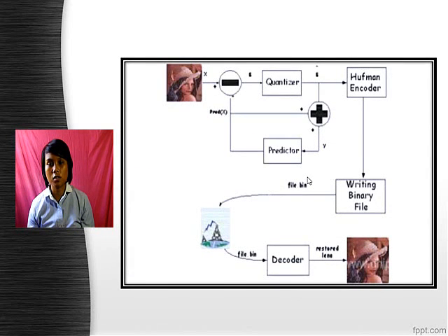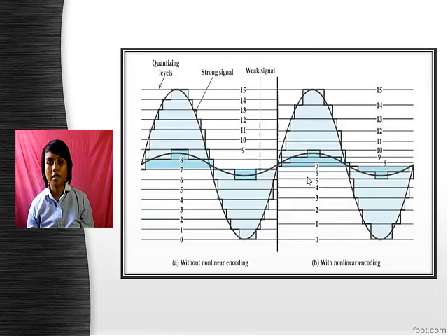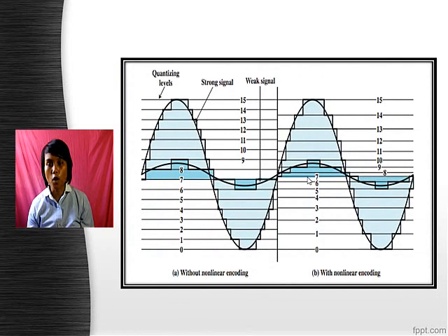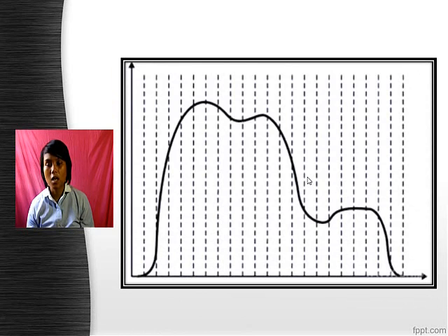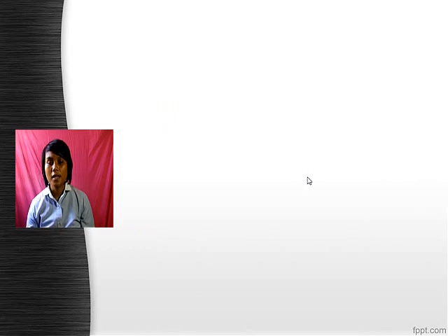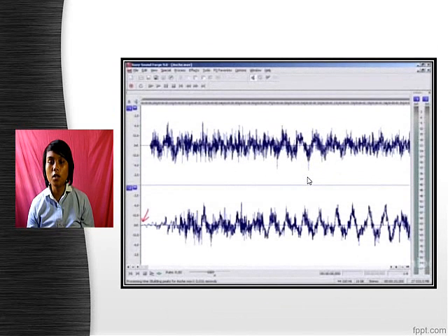Differential pulse code modulation encodes the signal in the form of the difference between current and previous values. For audio data, this type of modulation reduces the required number of bits per sample by about 25%. Adaptive differential pulse code modulation is a form of differential pulse code modulation which changes the quantization step to further reduce bandwidth requirements with a given signal-to-noise ratio. Practical application: first, the main digital channel, a digital 64K-bit stream. To obtain it, pulse code modulation is applied to human voice in electronic form. Second, WAV, a computer file format for storage of sounds, music, and voice.